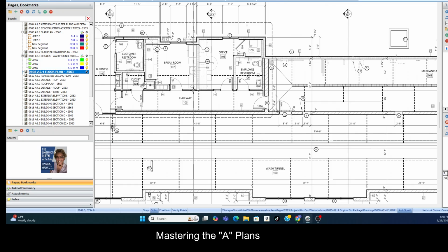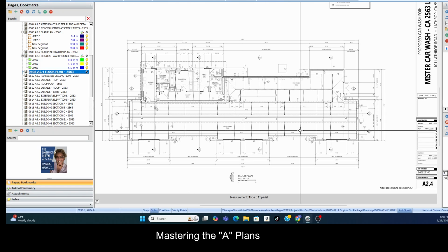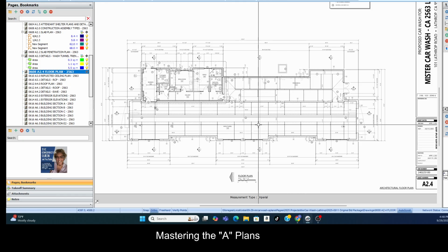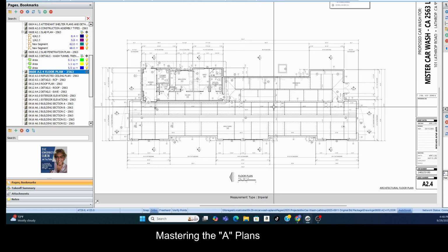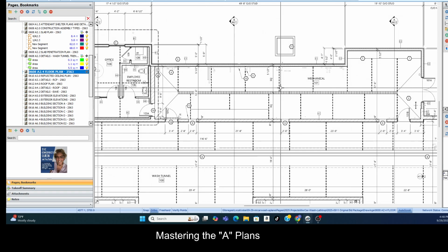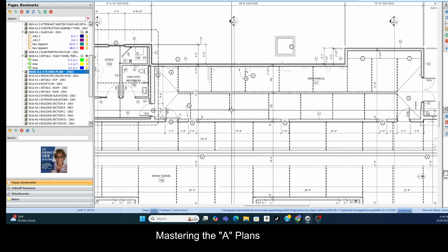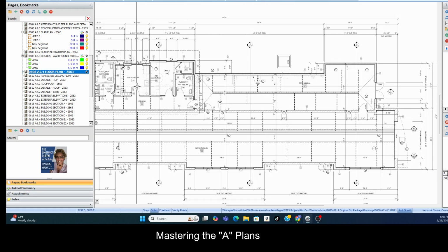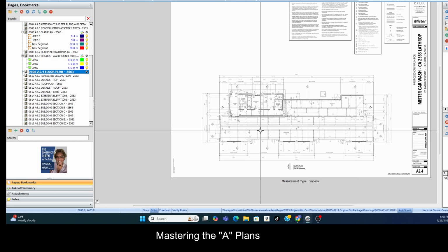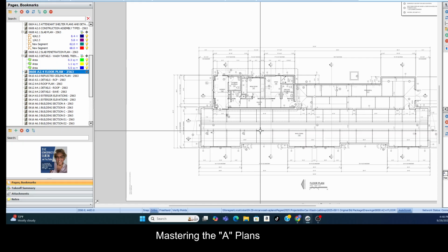I'm almost certain one or two of these that come in the building are structural walls. So that's the floor plan. All new walls coming from the floor up, and they're all marked. And all we've got to do is make our linears and then go to either the building section views or wall section views to determine the height. Next we're going to review the reflective ceiling plan.